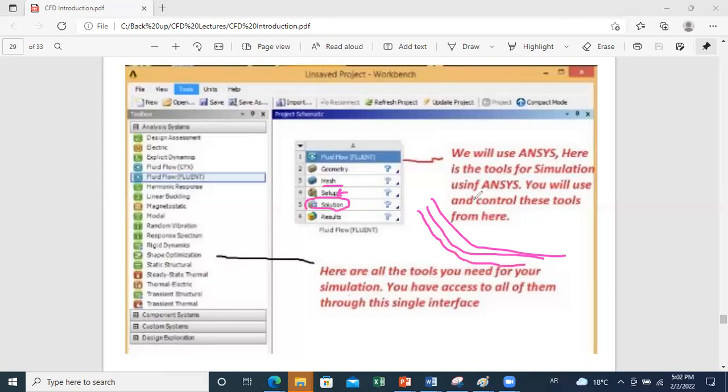Okay. Now in case you observe divergence, meaning the residuals are increasing, this means that your run is not going very well. Sometimes in some situations the residuals first increase and then decrease again, so we should wait some time. But if they keep increasing, this means that we can have divergence and we should try to enhance the mesh quality to have a better solution.